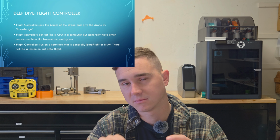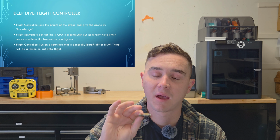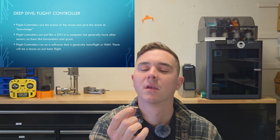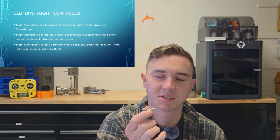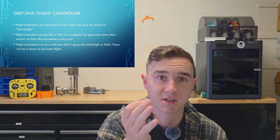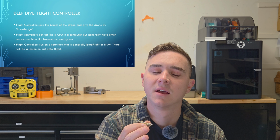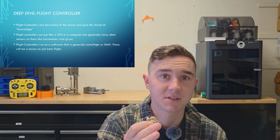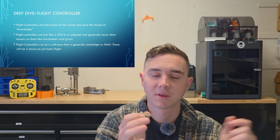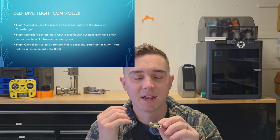I know that's pretty vague, but generally speaking, if I attach an ESC to this, with the little ESC plug right there, the flight controller is in charge of telling the ESC when to send power to each individual motor. It does this very, very fast. If I have a video transmit system plugged into the flight controller, it's responsible for sending camera data from the camera through the flight controller to the video transmit system. Same thing with GPS. It does a lot.